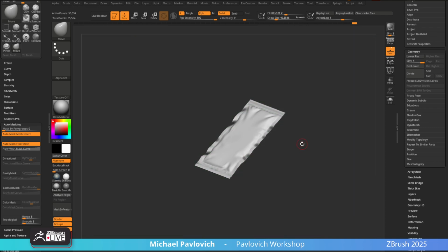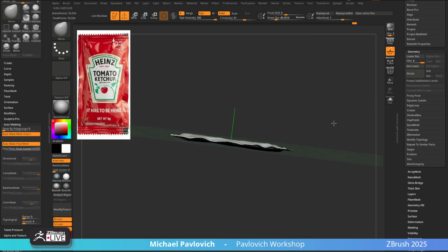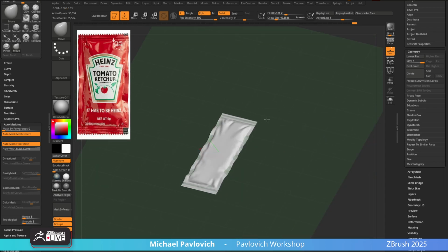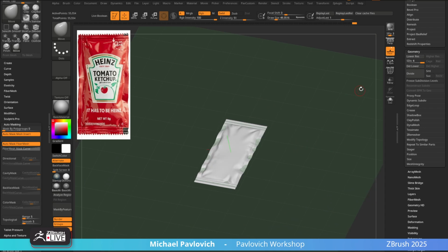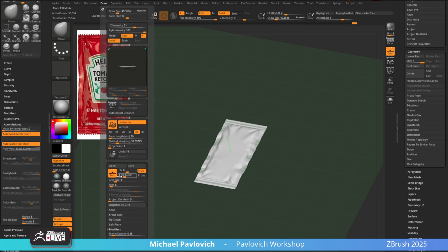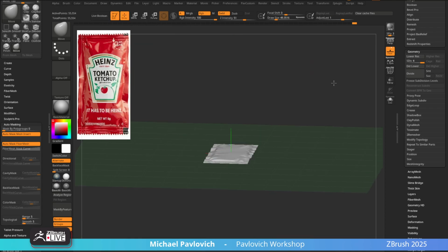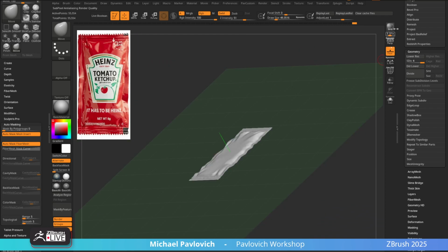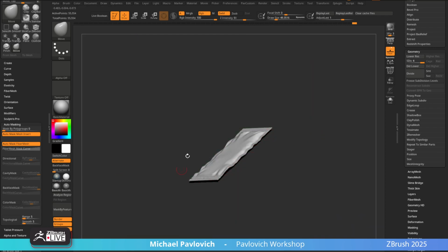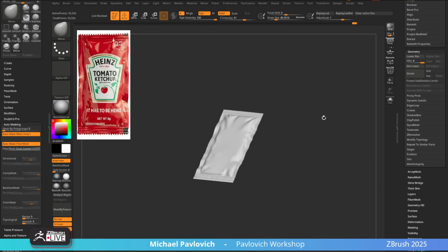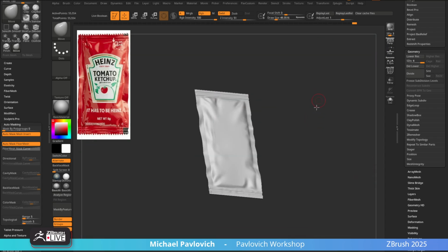Now, if you try to use the floor as a shadow catcher, it's going to catch a shadow right in the middle of your object, but at least that'll show you where the 0, 0, 0 world axis is, if you're a little more developer-y. But if you're an illustrator, just go in here to draw, and then set elevation to -1, and that'll move the floor plane down to wherever the lowest point is, and then again, you can use that as a way to catch shadows when you hit BPR render. Okay, what was I talking about? Okay, stress riser.